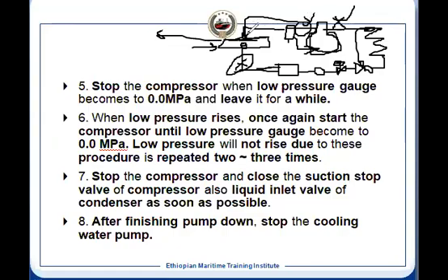Sometimes you may have a valve here, so you isolate. So your gas is contained in the compressor and the condenser, and it will remain there. So this is the pumping down or the pump down procedure. Is it clear, everybody? Any question? Yes, sir. It's clear.